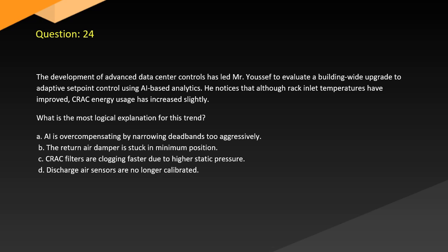A. AI is overcompensating by narrowing deadbands too aggressively. B. The return air damper is stuck in minimum position. C. CRAC filters are clogging faster due to higher static pressure. D. Discharge air sensors are no longer calibrated.